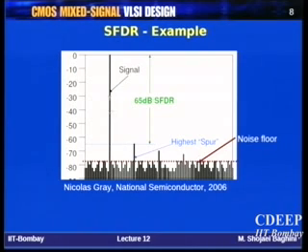For example, this is a signal with 0 dB power. The next harmonic is located here, and it is 65 dB below that. Therefore, your SFDR is 65 dB, and eventually it is called the highest spur. So, it's not only amplitude; it's also sometimes important for us to see at what frequency it is located.